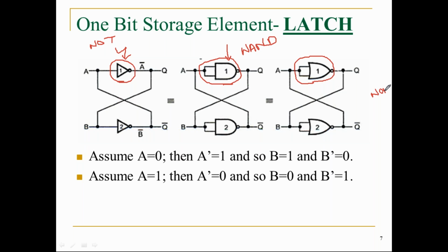What is the definition for NOT? Output is opposite to the input, or inverted from the applied input. What is the NAND logic gate according to the truth table? If any one of the inputs is 0, output will be 1. That is called a NAND logic gate.